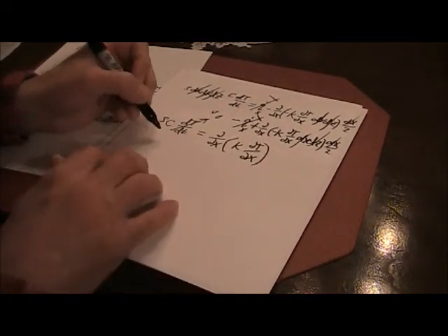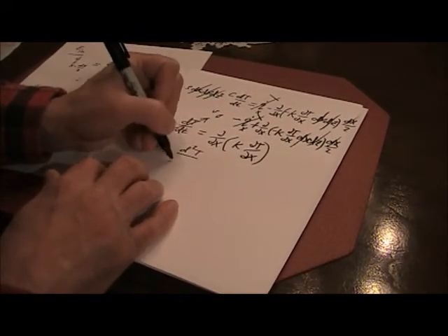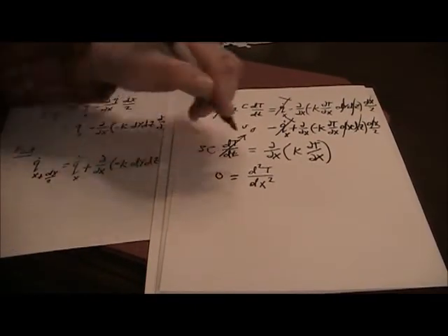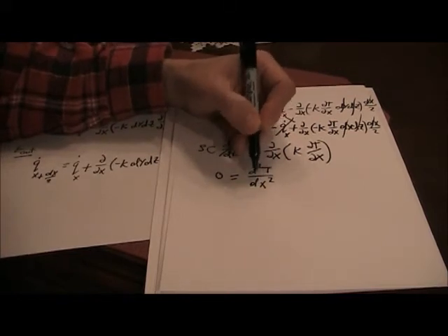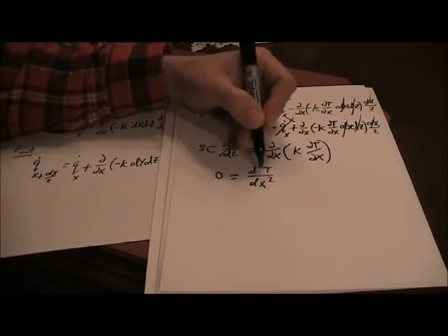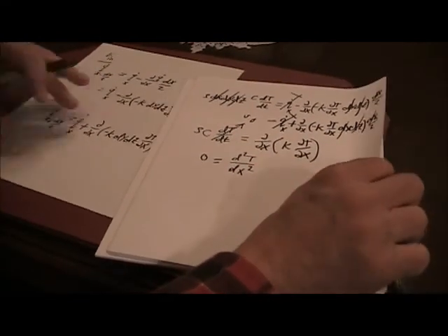So for this special case, what we would have is this right here. Two derivatives of temperature in x, so you would need two boundary conditions to solve this problem, because you would integrate twice and get two constants. So that's the heat equation in one dimension.